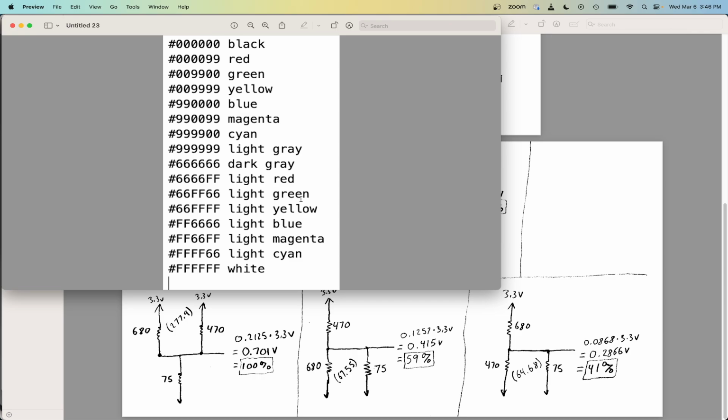Because we share a single GPIO signal for this lightness signal, that means there's only 16 colors because you only have 4 outputs. And so these are actually the colors you get. So here we get 60% levels on red, green, yellow, blue, magenta, cyan, and light gray. And then if you pull up the lightness signal, it increases everything by this additional 40%. And so it just adds that to those 8 colors to get these lighter ones.